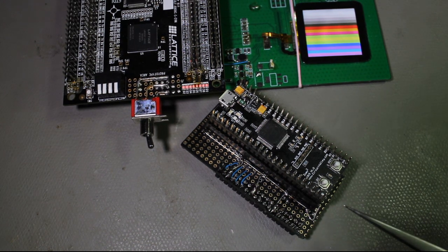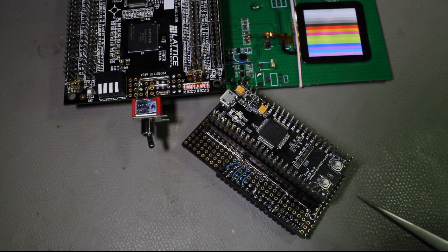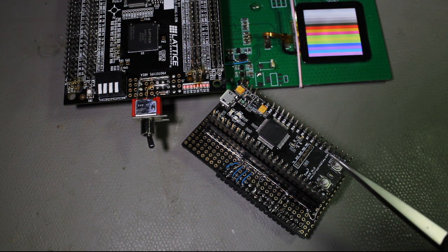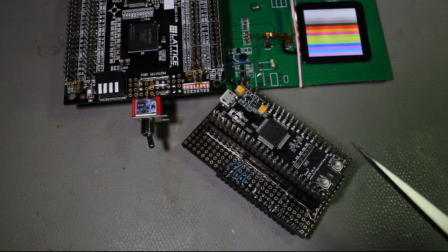The job of this microcontroller is to receive data over the USB from the Qt application and transfer it into the FPGA over the SPI. This microcontroller can only achieve a 50 MHz SPI clock rate, and because of some limitations in the DMA, even at 50 MHz, the bytes will have a little bit more gap than that.